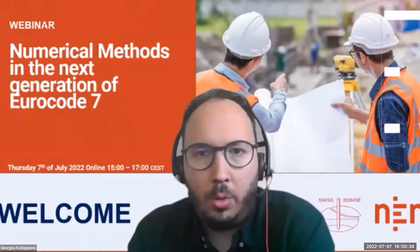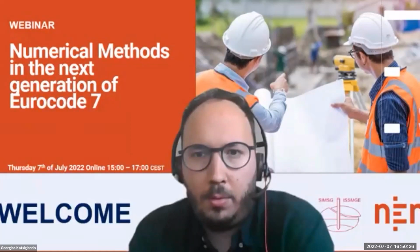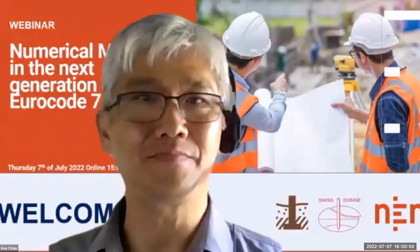There should also be a comment on dilatancy. For phi, the value depends on mesh size. We will not get a unique solution. I think that's probably beyond the remit of the Eurocode. That's a complicated issue. We know that if you've got non-associativity, then you don't necessarily get a unique solution, and you can get oscillations in your results. So I think that's one where it's down to the user of the model to know how to use that best and to interpret those results.